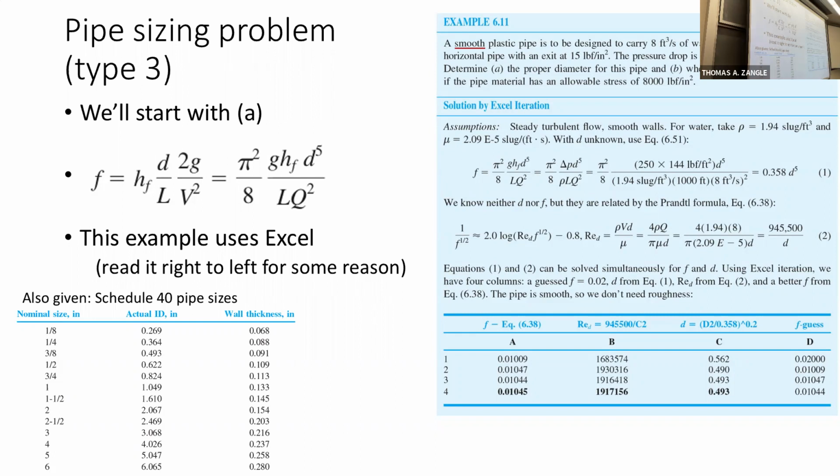Yeah, conceptually, why does the diameter have such a huge impact on, let's start with pressure drop. Previously we saw that pressure drop goes as diameter to about the -4.5, I believe, on the slide. Meaning that a relatively small increase in diameter has a really large effect on pressure drop, right? It really creates a large decrease in pressure drop.